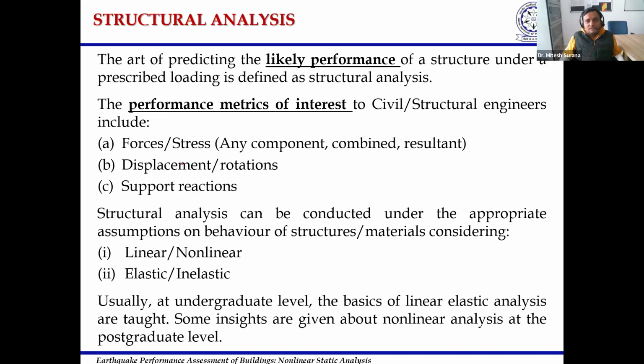So conventionally, we study linear elastic analysis of structures at the undergraduate level, because all the methods that we learn during our undergraduate studies in the civil engineering curriculum are particularly based on the assumption of linear elastic analysis. What do we mean by linear analysis? Linear analysis means the material or the system which we are analyzing actually follows Hooke's law. That means stresses are proportional to strain, or stresses are within the elastic limit.